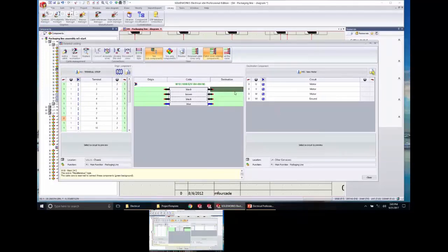You can select the end of the cable here, and then over here under the component, we have the number of wires, the terminal. This is the circuit information. So you click on here, and right now, 0 wires are hooked up to this terminal. So select both and then hit connect. As soon as I do that, I see there's 1 wire there, and then there's the reference. So I can do that multiple times, just left click and hold, and then select connect. And it's going to do it just in that order.